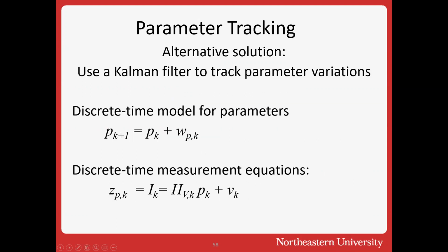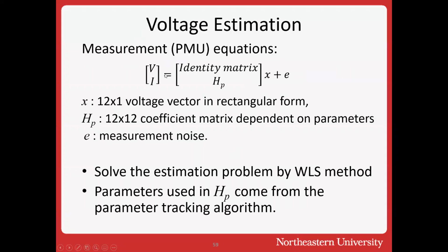So when you write this equation, we pretend that we can actually build this matrix H. But to build this matrix H, you need the voltages, but we don't know the voltages. I mean, we are measuring them, but of course, these measurements may be wrong. So we cannot really rely on the measurements, assume that they are perfect. So what do we do? Well, we better estimate those voltages, and we can certainly estimate them using this kind of linear state estimator for those 12 voltage values, unknowns.